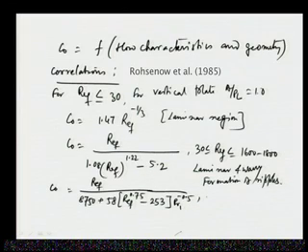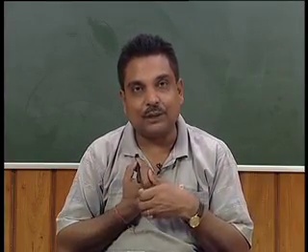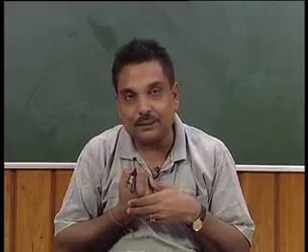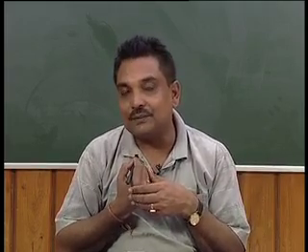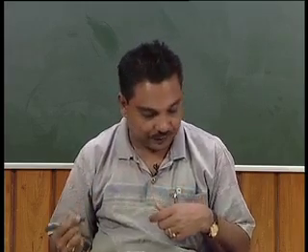And here Re_f is greater than or equal to 1600 to 1800. So, that means it is the case of turbulent flow. These are the relationships available for the condensation number or modified Nusselt number, based on the Reynolds number, and once we know the values of Reynolds number, we can find out the values of this, and then we can find out the values of the heat transfer coefficient.